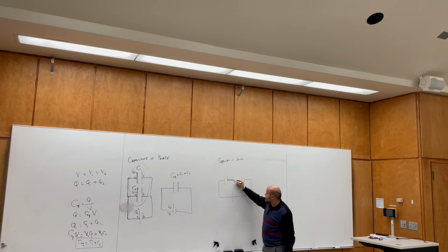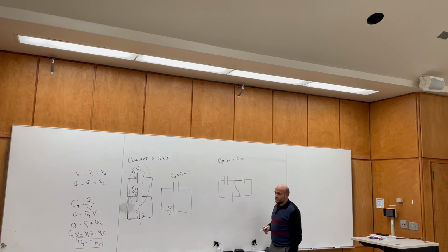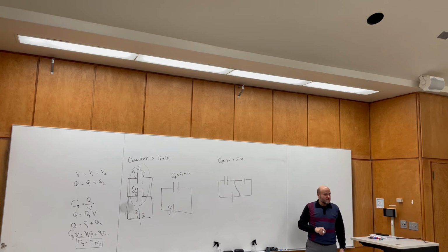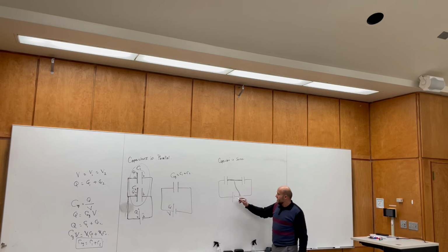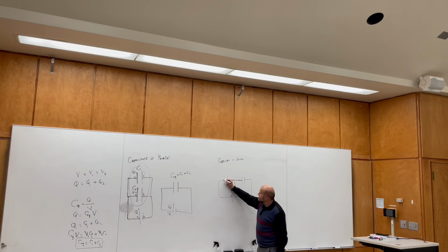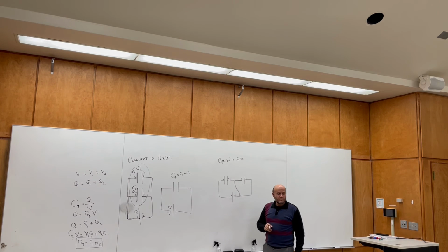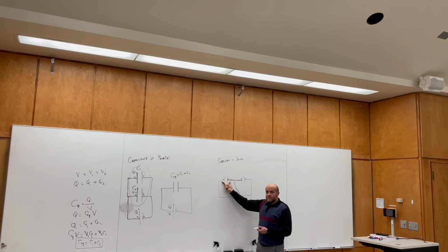Like if there's a wire like this, there's a junction. These are not in series anymore. So it has to be just one wire without any junction, then they will be in series. For the voltage, if this is A, then this is B, then this is B, and this is C, and this is C. AB, BC, AC, different voltages.